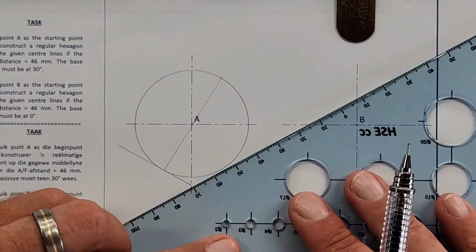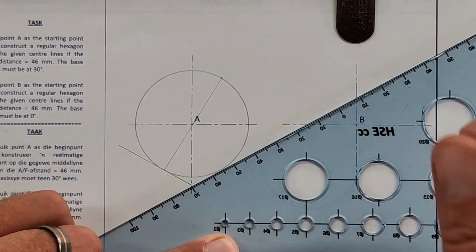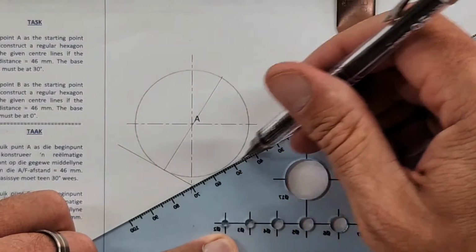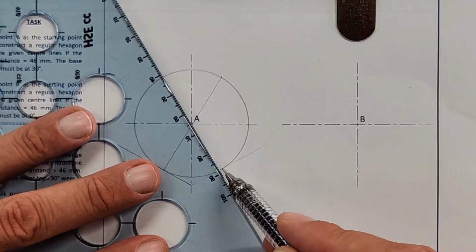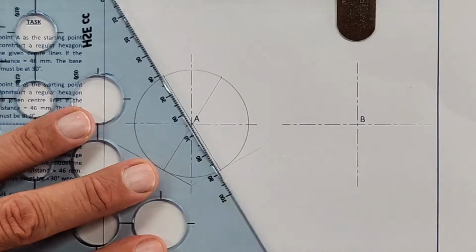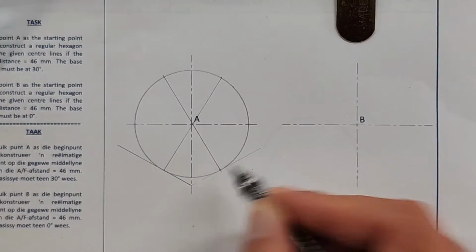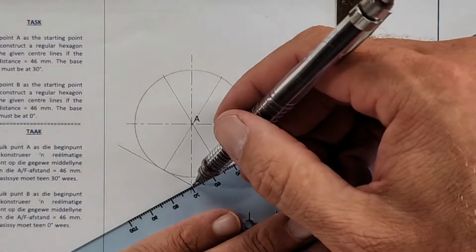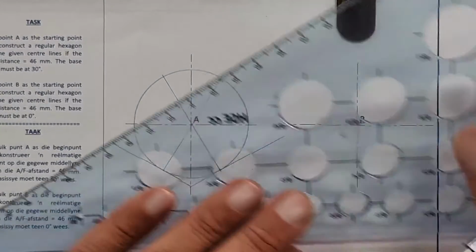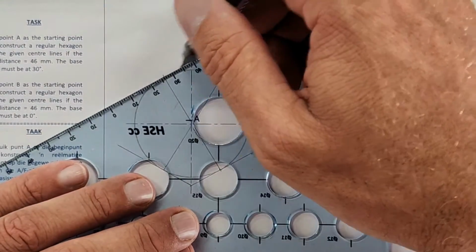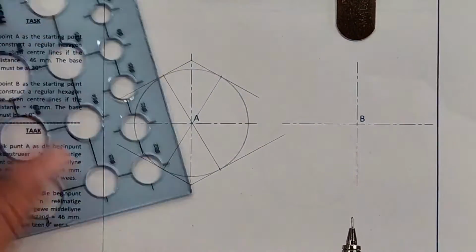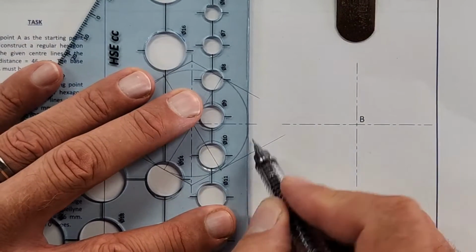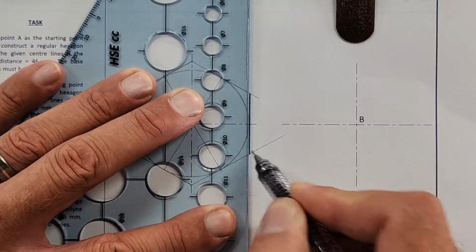Now I can go guess it, and you probably will be right, but just for the sake of it, that tangent is at 30 degrees, so it must be perpendicular to a line that is 60 degrees, and that tells me the touch point of this line. So I now can go in construction, and it touches here. The same on top, that line I can already use there. Construction line. Construction line. And I can draw it now nice and dark. That line is already clear for me. Duidelik en uiteindelik. Daar gaat hy.